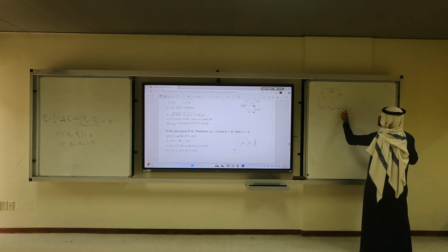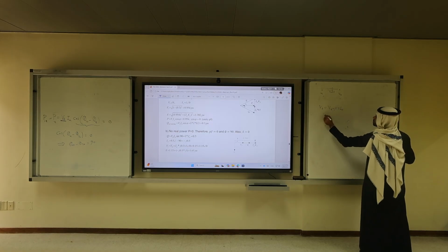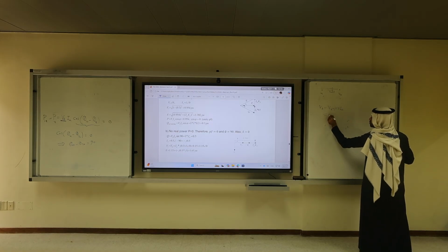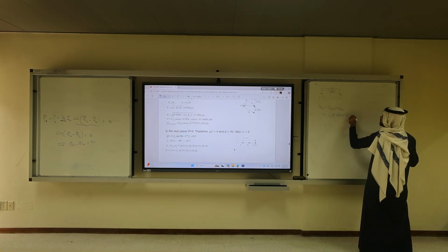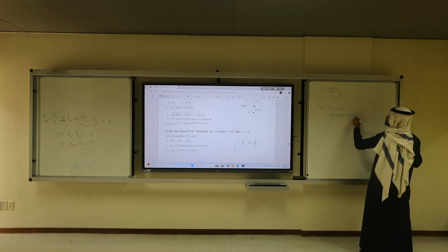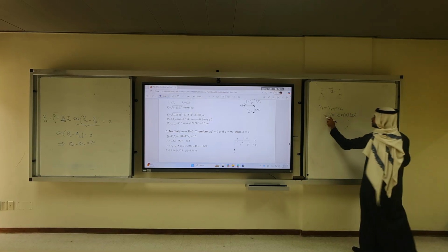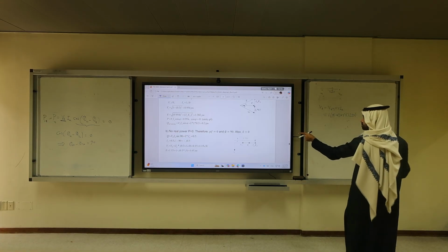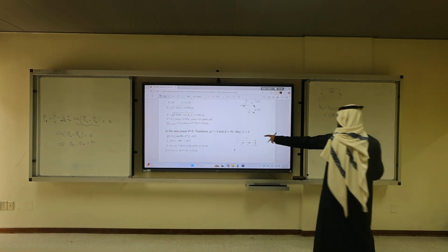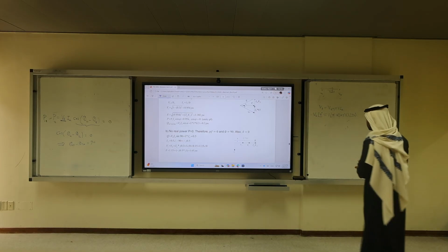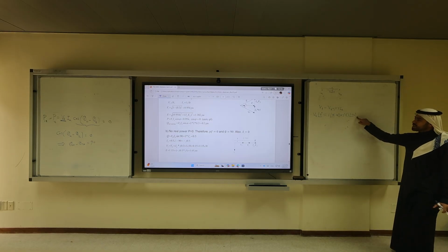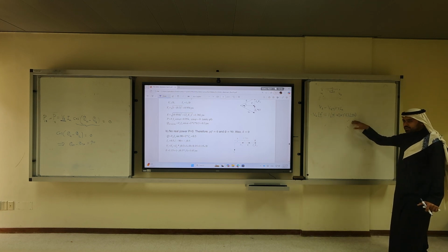You agree with me? But now there is a j here. Now he is telling you that this is Vb, which is 1 at an angle of alpha, plus j0.3 times Ia, which now is 1 at angle minus 90. And this should equal Vt, so you should get a new Vt, at an angle of 0, we're taking it as a reference. That's the change, and then you have to repeat the same story: the magnitude of this equals the magnitude of that plus the magnitude of that.